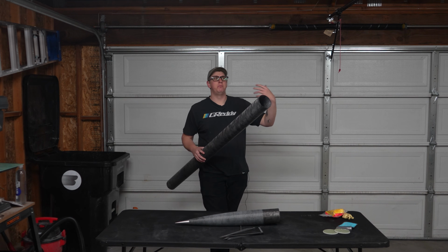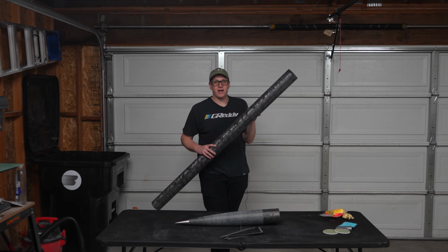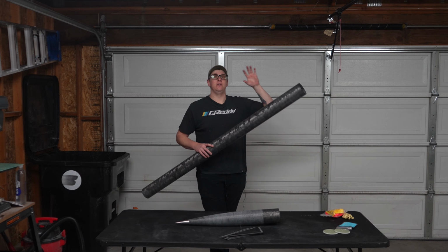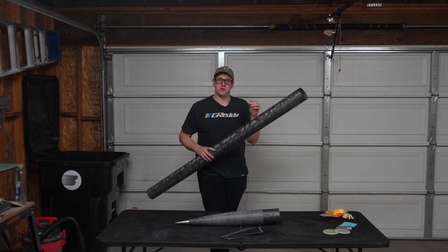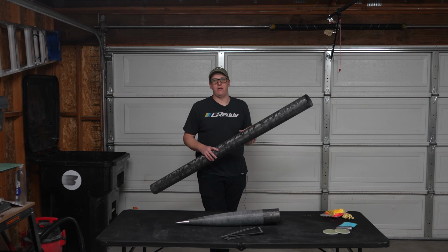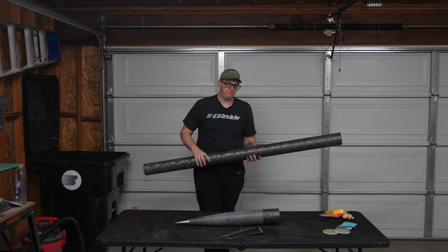And most importantly, you want to measure the actual center of gravity of your rocket in real life and the actual weight of the rocket so that you for sure have those 2 elements complete. Once you have that and the correct measurements of your fins and your airframe and all of that, you should be getting very, very accurate sims.